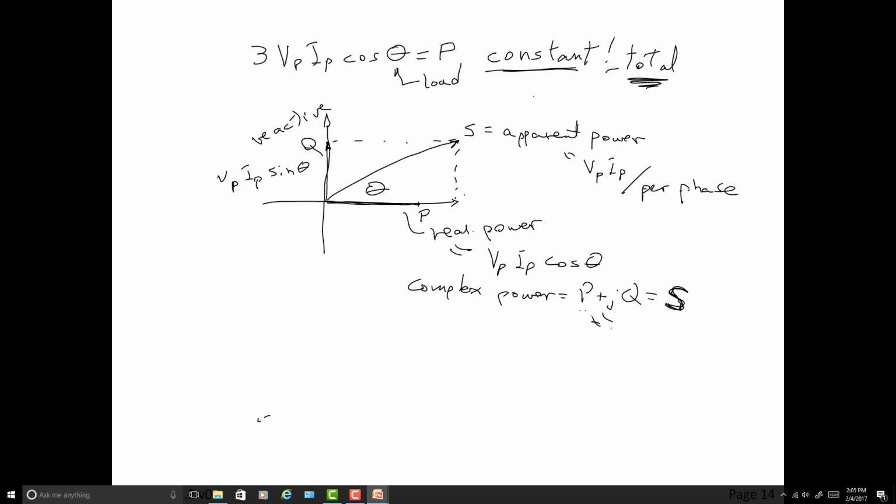And this is going to be the voltage times the current, but if these are phase related, it's got to be conjugate math. Okay, so remember to do that. And then so the total power, or the total average power in all three phases is simply the sum of these individual powers. So that's the power total will be 3 times the power per phase.